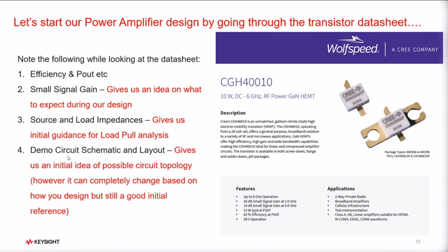Most data sheets also give you a demo board circuit schematic and layout that again may not exactly work one-to-one with your expectations, because they might be using some other dielectric, you might be using some other dielectric. And most of the demo boards, since they are for demonstrations, usually do very, very broadband kinds of designs. In your actual applications, you don't need to do that kind of broadband design.